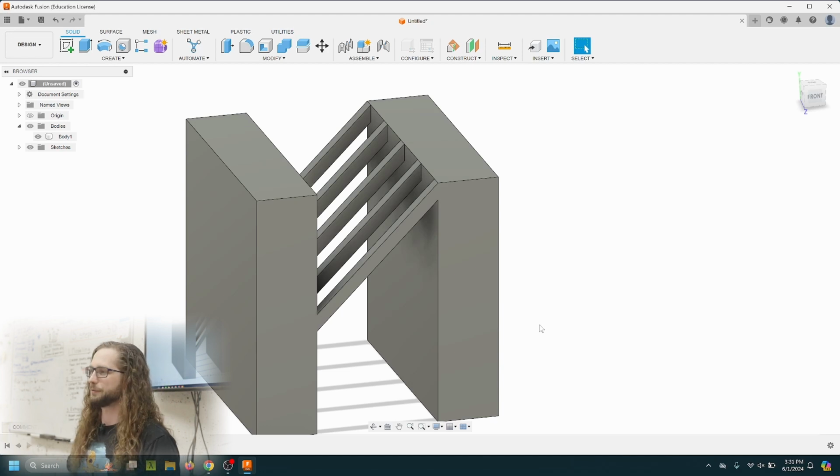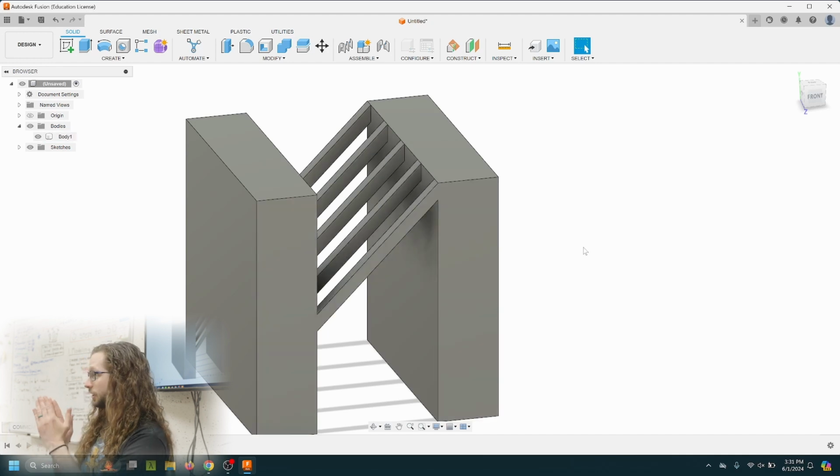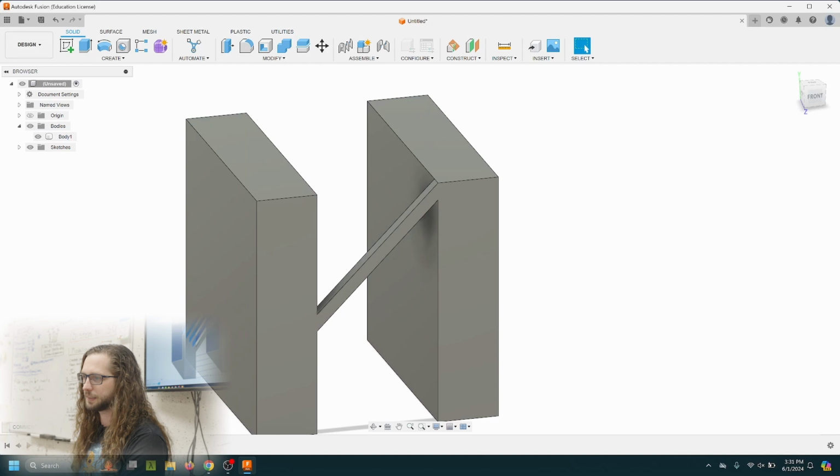The way that we could express this here is to say, well, these spans right now are rectangular because I used the extrude. It just came straight out. But what if I actually wanted these to be triangular or oval or some other shape? So I'm going to back this up a little bit. I'll delete the pattern and I'll delete the extrude.